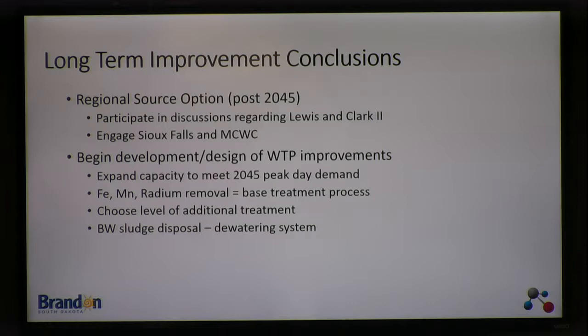You do, and I don't. So to answer this question, I did a hypothetical. We've got customers using 6,000 gallons per month, and you're only going to soften a portion of that, maybe 40 to 45% might go through your softener. So assuming that value, assuming the cost of salt, and assuming the decrease in hardness from 400 to 200 milligrams per liter of that water going to the softener, it's about $2.60 per month.